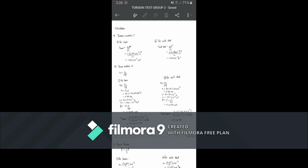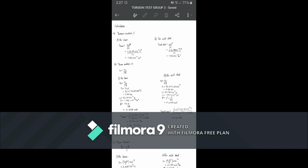By using the formula J equals pi d to the power of 4 over 32, we will get the answer after we insert the values, that is pi and the diameter given, over 32. The same thing goes for mild steel. We also use the same formula, pi d to the power of 4 over 32, and after we insert the values, we will get the answer.